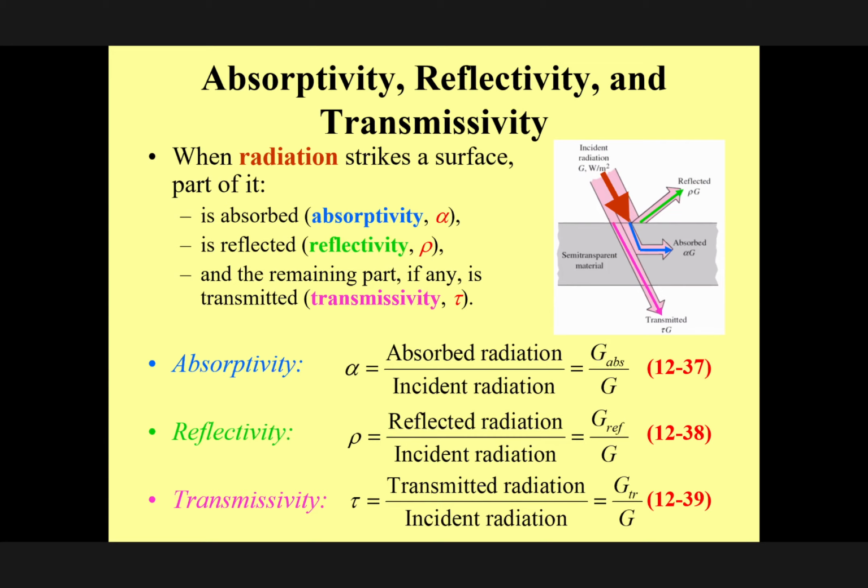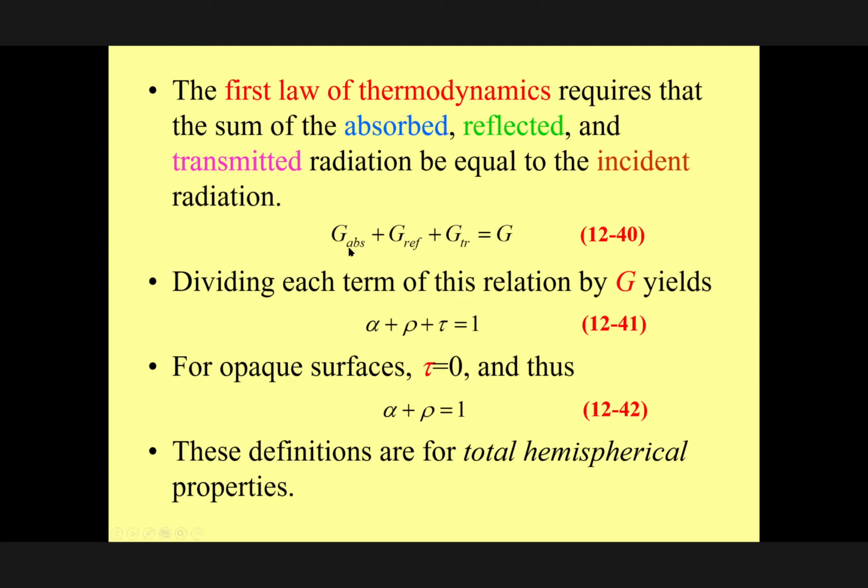Okay, therefore down to now, if I say a certain amount of energy G comes here, that portion will be reflected, that portion will be absorbed, that portion will be transmitted. If I write a simple energy balance for this surface, I can see a relationship between the variables rho, alpha, and T. If I say portion absorbed, portion reflected, portion transmitted, it is equal to the total energy that comes here. Therefore, we have this relationship between these properties.